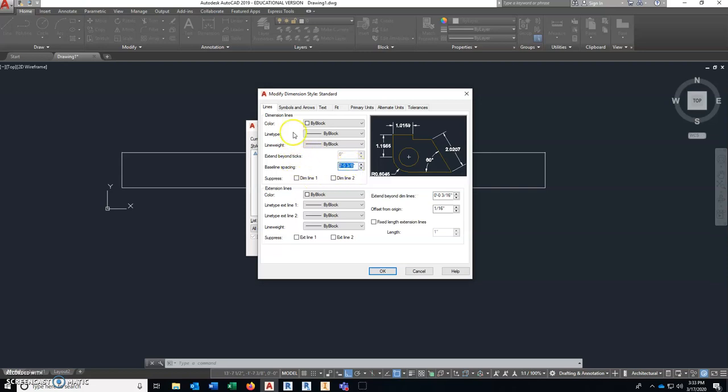We can do another video later on how to figure all that out and how to set up your scale factor and text height sizes. But for now, just know that on a residential drawing, if you want your text height to be a 1/16 of an inch when plotted, you need to use 3 inches in all of this stuff.